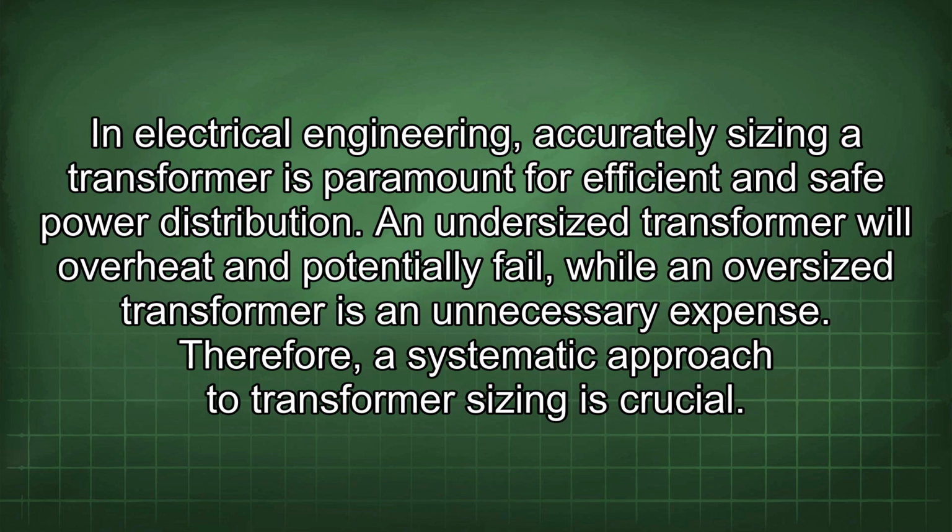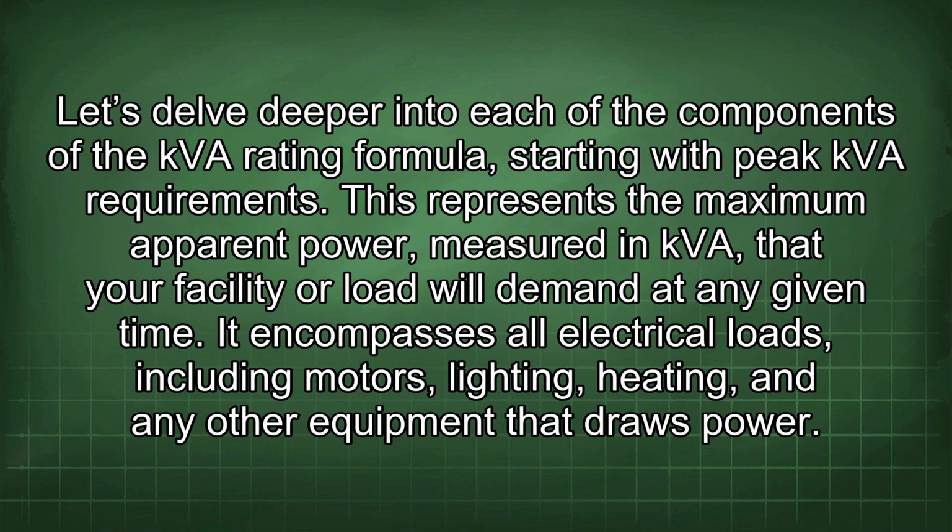In electrical engineering, accurately sizing a transformer is paramount for efficient and safe power distribution. An undersized transformer will overheat and potentially fail, while an oversized transformer is an unnecessary expense. Therefore, a systematic approach to transformer sizing is crucial. Let's delve deeper into each of the components of the KVA rating formula, starting with peak KVA requirements.